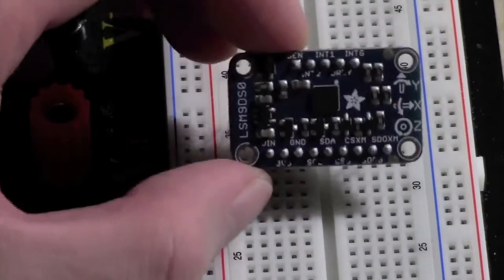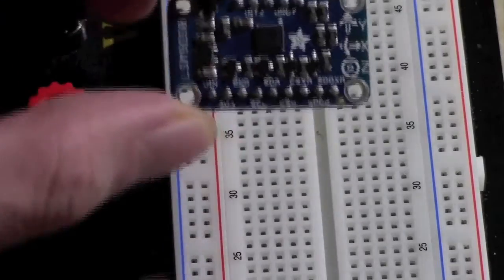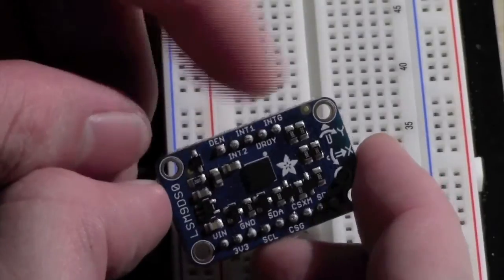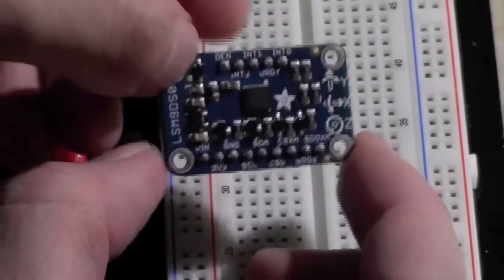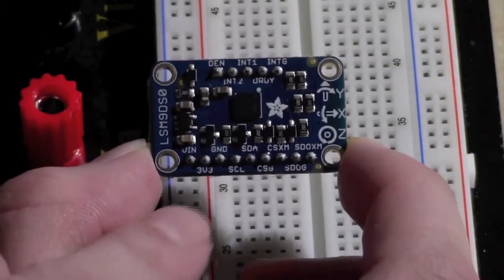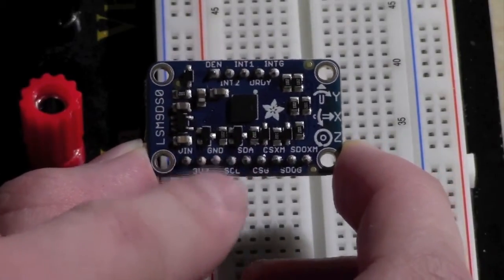With that as well, there are also a few pins that you might need to know. There are ones on the top right here, but these aren't necessary. These are for interrupts if you want to use them, but we're not going to be using them. Alright, so the bottom right here is 3.3 volts, ground, and again, this has an I2C interface, so you're going to see a serial clock and SDA as the I2C pins.